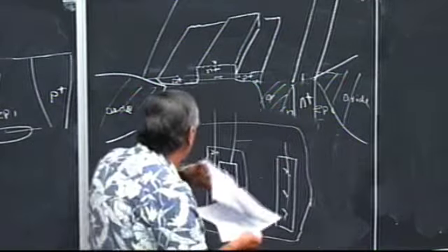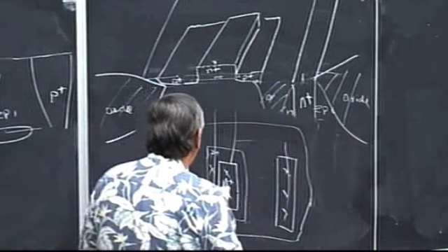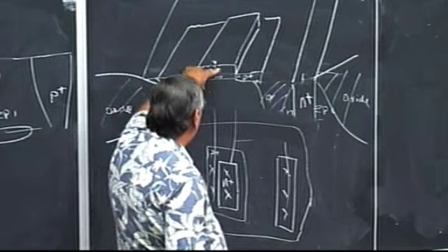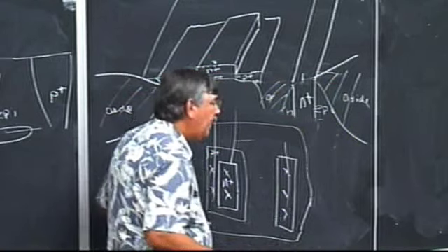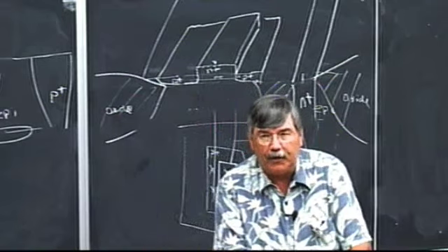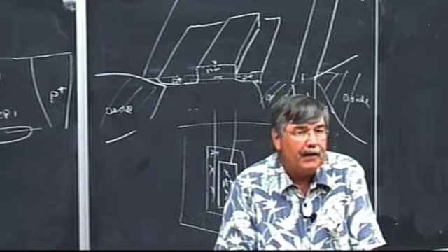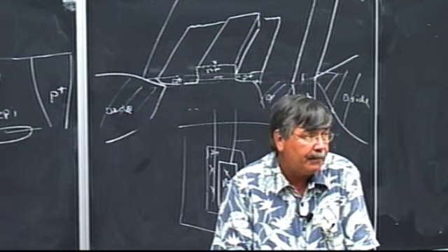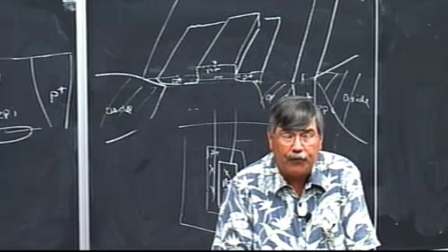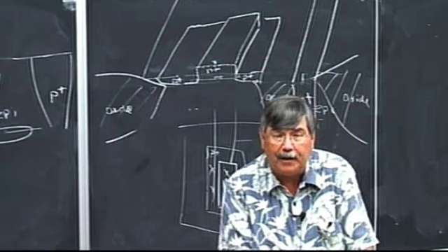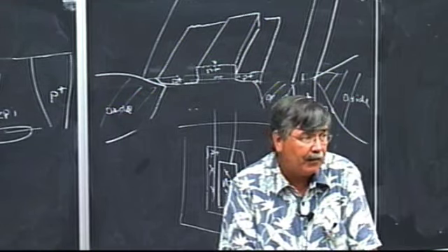Let's go back in one of these standard processes and just understand what happens. Well, this has been optimized for this nice NPN device. As a circuit designer, we really want to have access to a complementary device. The NPNs are good. The electrons are faster than the holes. They have higher mobility. So we like NPNs for most of what we're doing. But as you'll see, it's really nice to have a good PNP transistor.